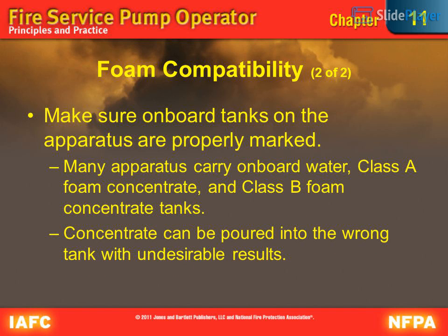Foam compatibility, 2 of 2. Make sure on-board tanks on the apparatus are properly marked. Many apparatus carry on-board water, Class A foam concentrate, and Class B foam concentrate tanks. Concentrate can be poured into the wrong tank with undesirable results.